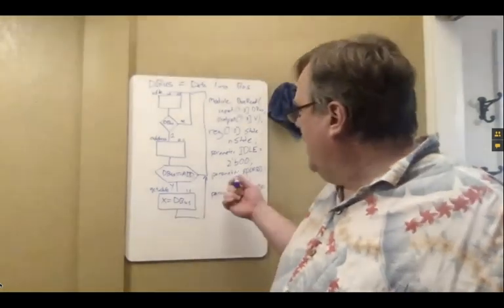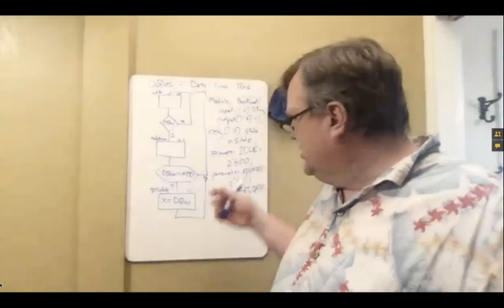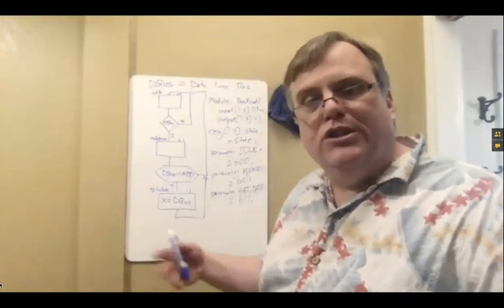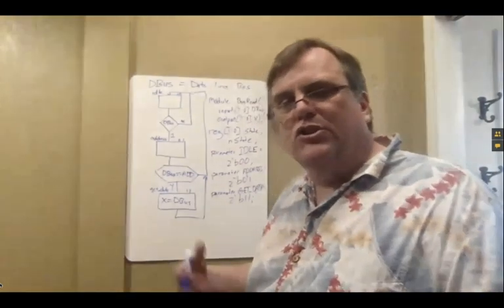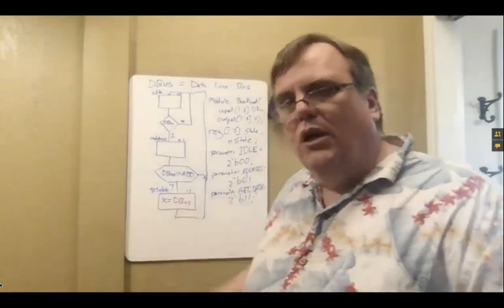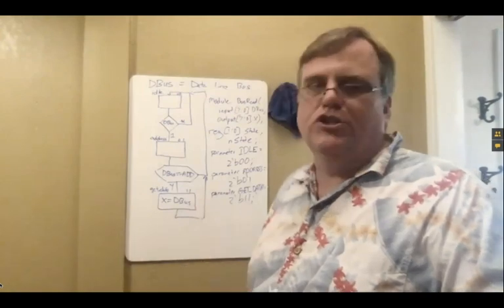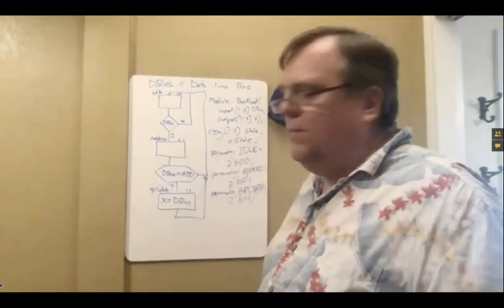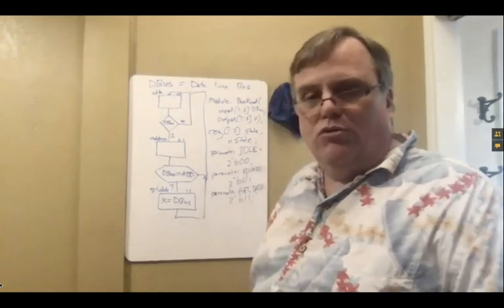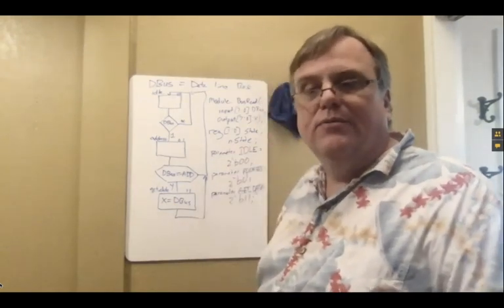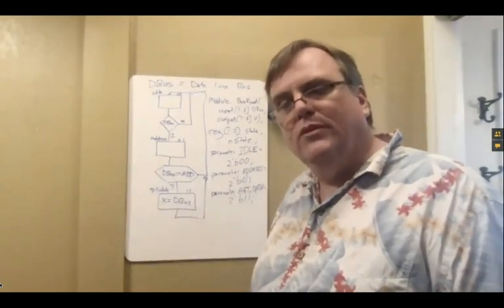I would pick a param if I wanted them to be able to override my choice, because I just kind of picked it for my own usage, what made sense, and they might say, no, no, no, I don't like that usage, I want to override. So that's really the difference between param and local param, is whether somebody external can change it. So I'm leaving it open for people outside to change it, because I'm saying this is not the end of the world to me, as long as you do it consistently. And modifying here, it'll consistently change it all the way through.